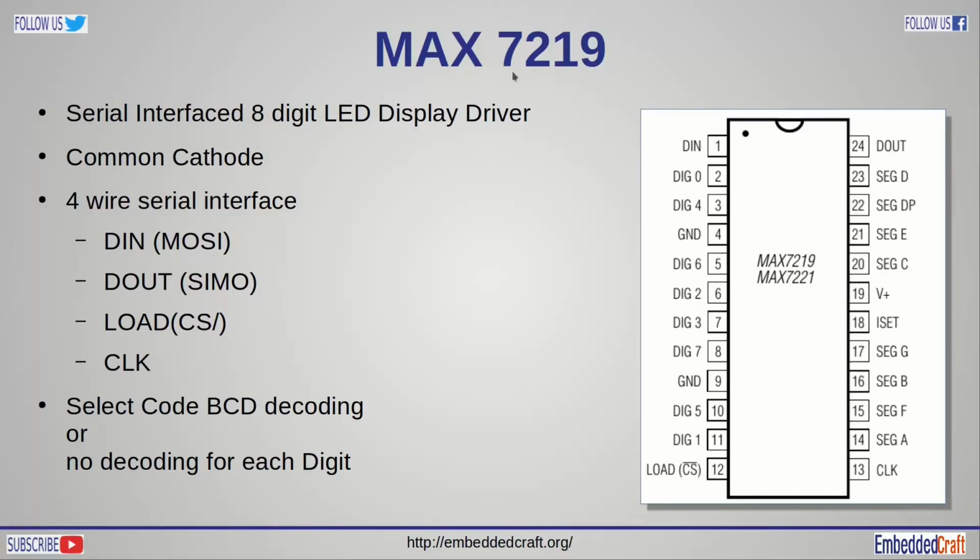We will use the MAX7219 SPI interfaced LED display driver IC. MAX7219 is a serial interfaced, 8-digit LED display driver. It has a 4-line serial interface. DIN is the MOSI line, DOUT is the MISO line, LOAD is the chip select line, and here is the clock line.